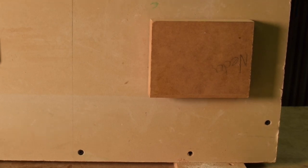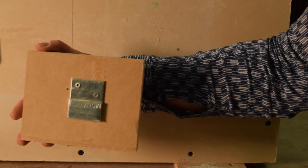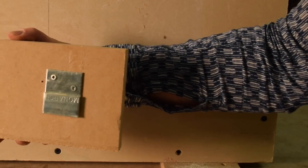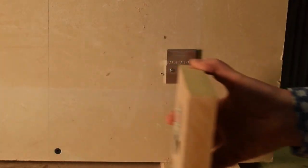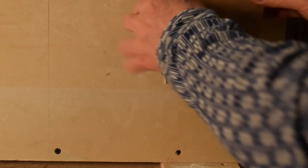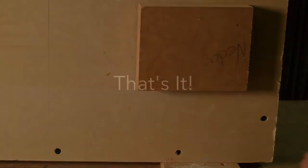Here's a small block that I'm attaching to the wall with those Z clips. Now this Z clip can be screwed onto the back of the piece that I'm mounting, but it could also be glued on. And that might be really helpful if you were mounting, say, a piece of glass or ceramic that you can't actually screw into. And the piece just slots on over the Z clip portion that's attached to the wall.